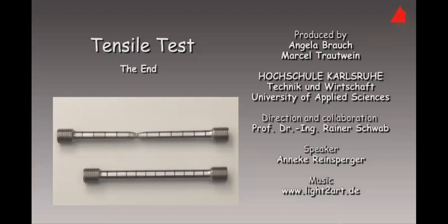As far as this video is concerned, two materials are tested. The first one was showing some ductility, so there was a yield phenomenon, there was an upper yield point, a lower yield point, everything was there. In the second material there was a little bit low ductility, so that material wasn't showing any yield phenomenon. As you go on increasing the load, at a certain point it will leave its elastic limit and directly enter into plastic deformation. During this transition, there will not be any kind of jerk in the force. So that is the specialty.